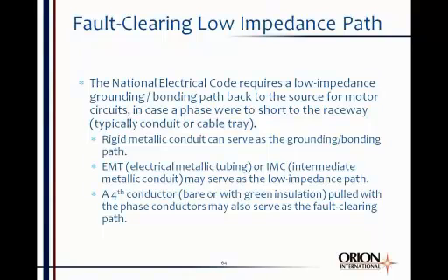But if you're going to run the circuit conductors in PVC conduit or fiberglass conduit or some kind of an insulating conduit, you have to pull a fourth conductor, which will either be bare copper or green insulation is allowed, and that will serve as the fault clearing low impedance path.